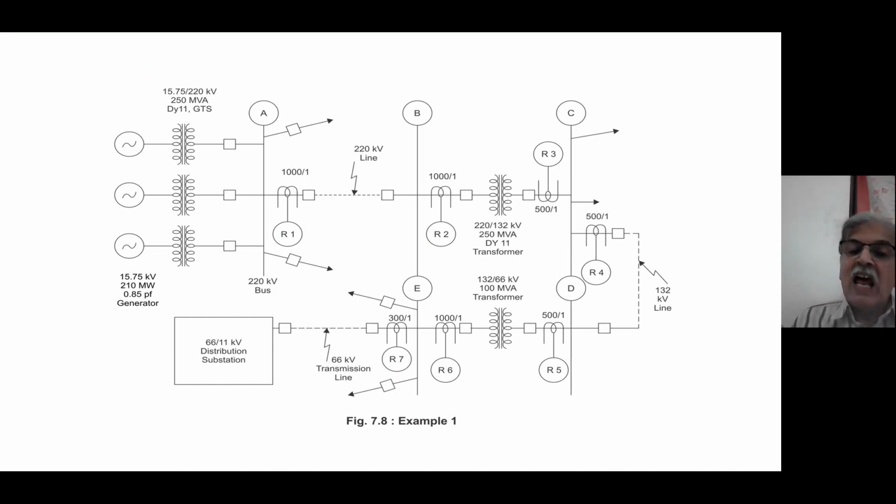So we start with the last relay, R7, obviously. R7 depends on the full load current, because for a phase relay, meaning R, Y and B, full rated current is going to pass. If it is a ground relay, it is going to be different. But now, when we are talking about a phase relay, normal current is going to pass, and your setting has to be higher than the full load normal current. That is very obvious, right?